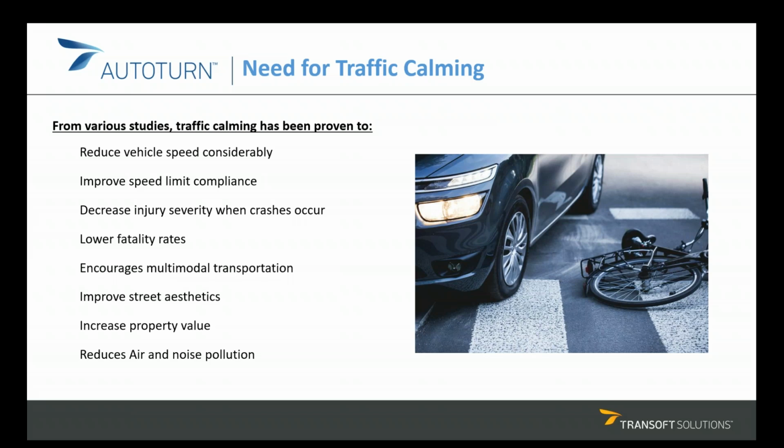Studies have shown that traffic calming can reduce vehicle speed and volumes considerably. Some regions found a drop of more than 10 to 16% in the total traffic volume and found that more vehicles were traveling at a speed which is less than 23 miles per hour after implementation of these traffic calming measures in the United States. The accident levels were found to drop by 40%, and also the fatalities due to these collisions were reduced by 33%.